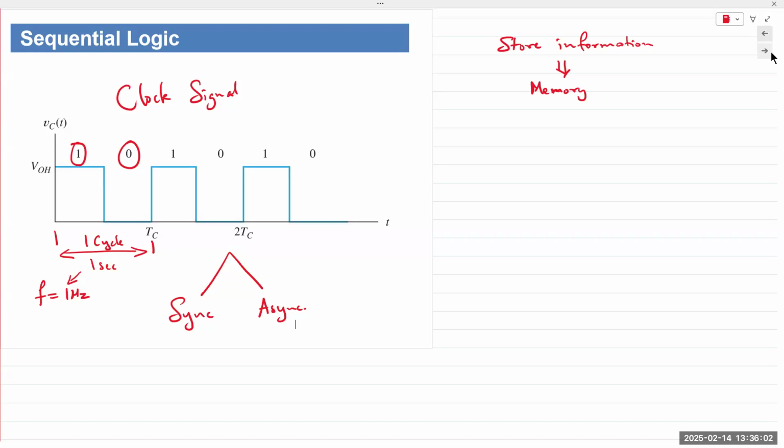60 cycles. Anyway, the point we're trying to make is the voltage goes from 0 to a positive value and back to 0, a sine wave. So we have 1 half cycle. Then it goes from 0 to a negative value and comes back up to 0, the negative half cycle. 1 full cycle is a positive peak and a negative peak. And the number of times it goes through a positive and negative peak in 1 second is the frequency of the waveform. So in North America, the voltage at the power outlet goes to a positive and a negative peak 60 times in 1 second. That fast. But 60 hertz is a very low frequency. My ears probably can't even distinguish between those sounds.